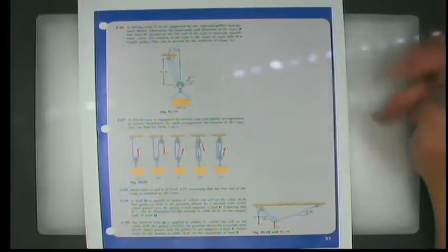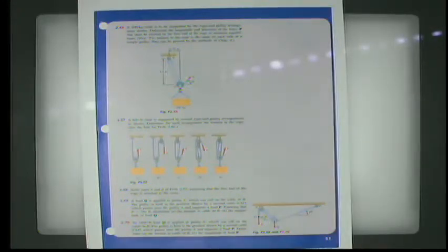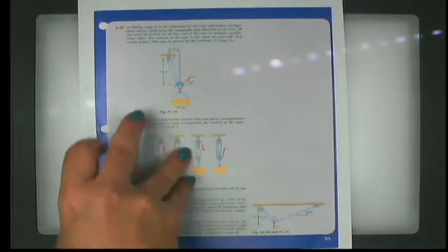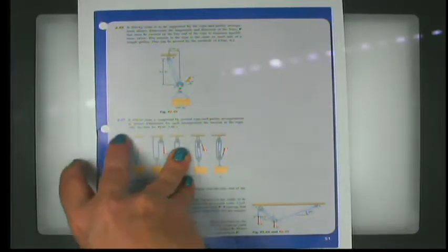So this is actually how block and tackle arrangements are constructed, because if you have half the weight, you have to pull twice as far to make it go up because you're pulling twice the rope. So you do the same amount of work, but you actually reduce the force by using pulleys. And that's something they do a lot in industrial applications, especially in olden days, even before I was around. To move something heavy or to move something in a position that's difficult for a human being to move, these things can make something go from being impossible to being possible.